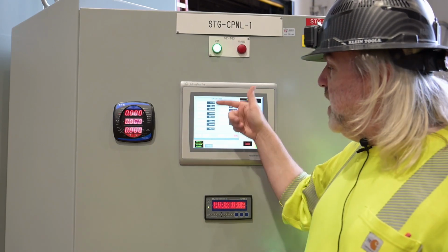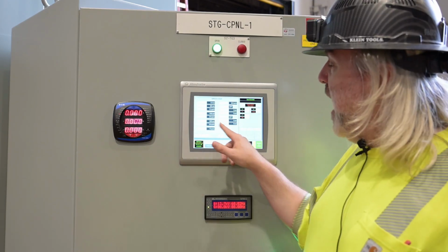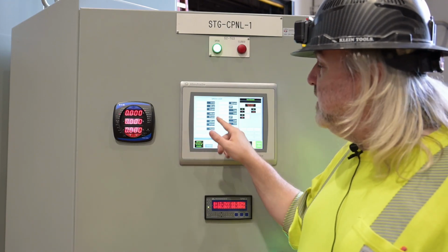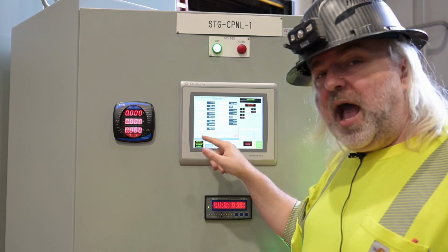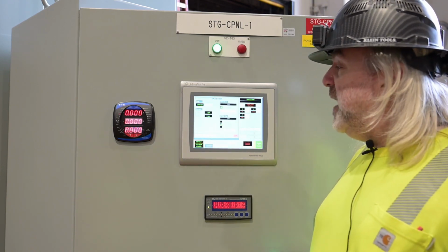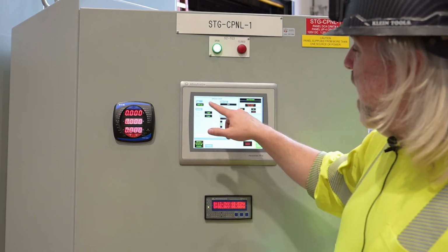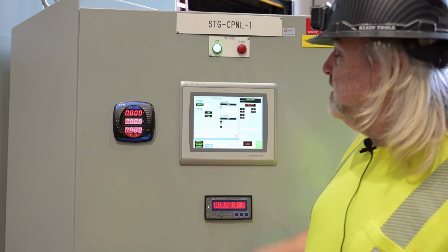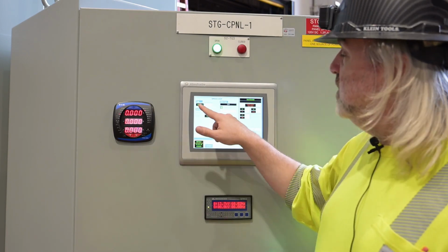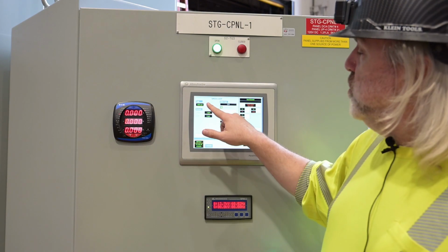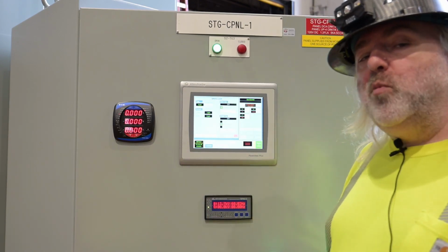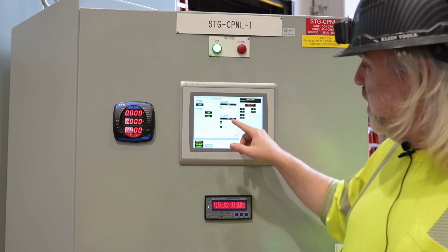Config is a little different because we have a speed ramp where we have to do different RPMs at different points. This is where you can go to see the different idle times, rated times, and such. Last thing is test. Under speed, we have a test function. We have a peak. In this case, you can see that the last peak speed we had was 1958 RPM. You can reset that. So every time you do a test, you can use this peak to record what your peak speed was on the test.